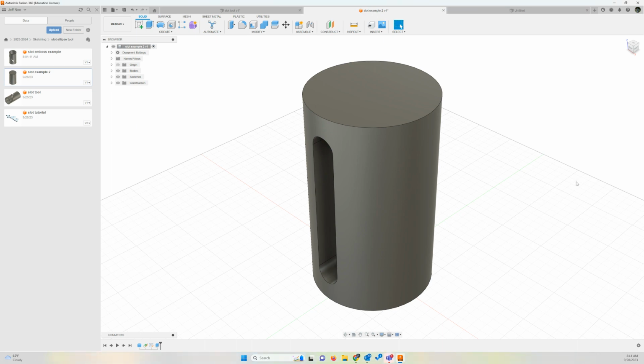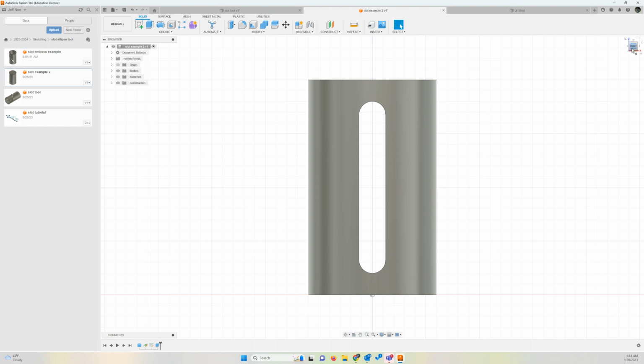If you look down at the timeline, you'll see the cylinder icon here, so you don't have a sketch and an extrude. We're then going to sketch on a construction plane. We're going to create a tangent plane. We haven't done construction planes yet. So we're going to create a construction plane on the side that's tangent to our design here, and we'll create a slot on it, and then we will cut it through the face or through the design, creating this opening.